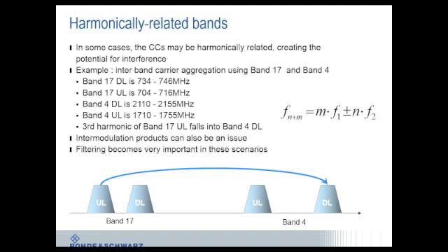For now, we don't see this as a huge problem because the uplink power is significantly less than the downlink power. But as the frequency spectrum evolves over time, what happens if a high-powered downlink signal creates an nth harmonic that falls into the uplink allocation of another band? Well, this is much more detrimental and is something to pay especially close attention to. Going forward, having a good methodology for this kind of testing with interference is also going to be very important. Be prepared with the right filters to verify these types of issues. They come in handy.